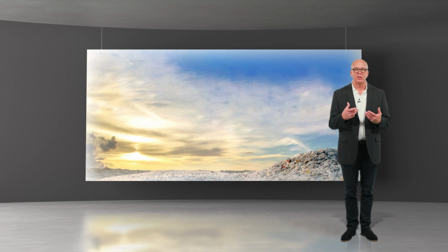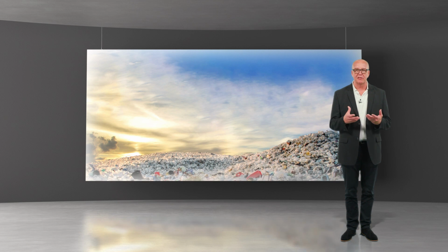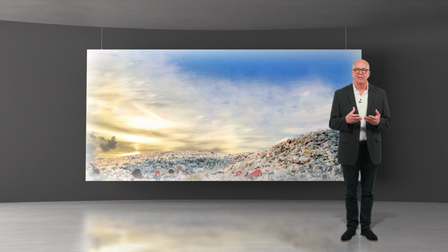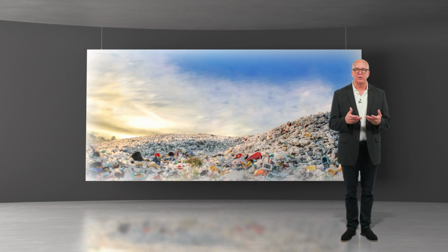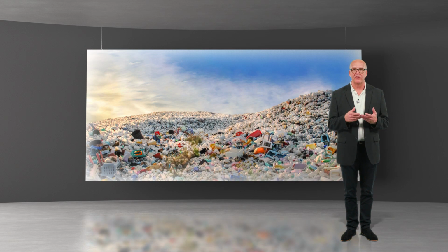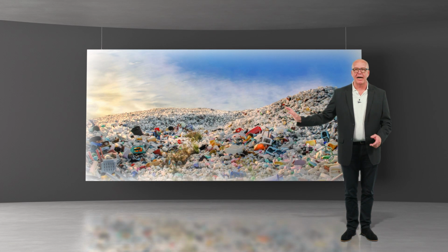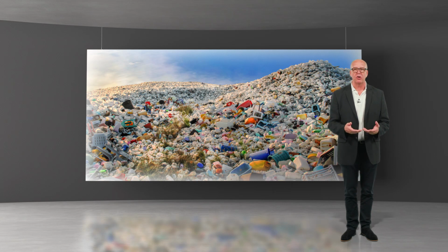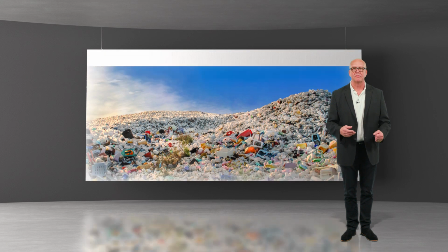Another point to be considered in the design is height. The ground, bottom liner, drainage system, and so on cost money. Therefore, the landfill should be as high as possible to minimize costs. Big landfills should be designed for an average height of at least 15 meters, better 20 meters.